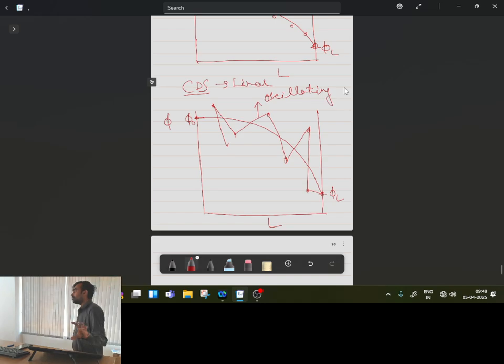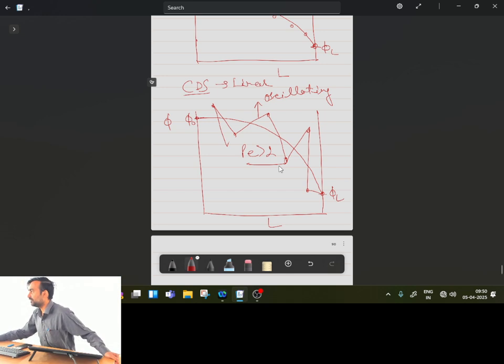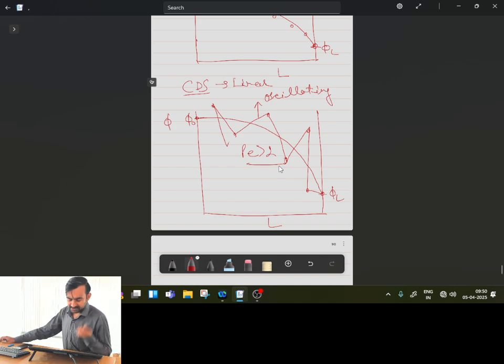It is not following a particular trend, and this will be for Peclet number greater than 2. As you move far away from the Peclet number 2 condition, these oscillations will become more rigorous and you will not be able to make any conclusion out of the results you are calculating. So can you tell me what could be the possible reason for these oscillations in my solution when the Peclet number becomes greater than 2?